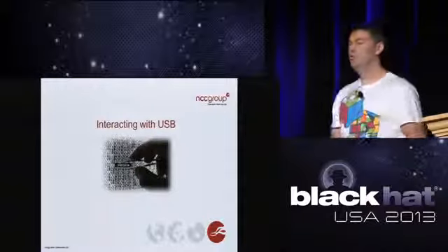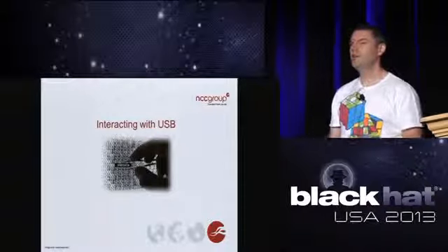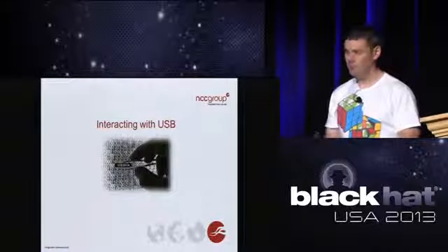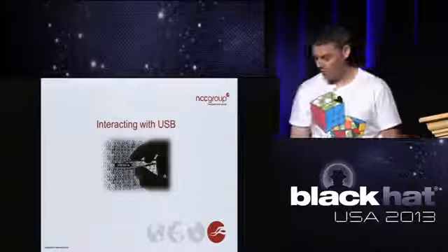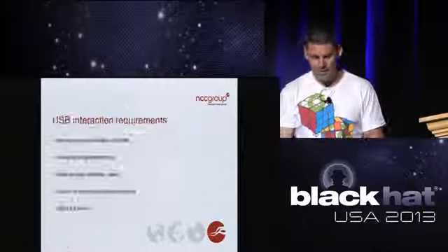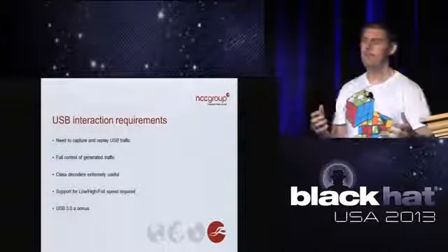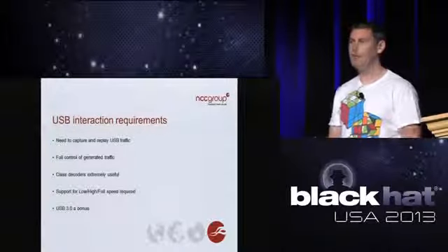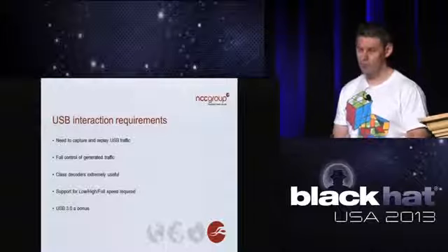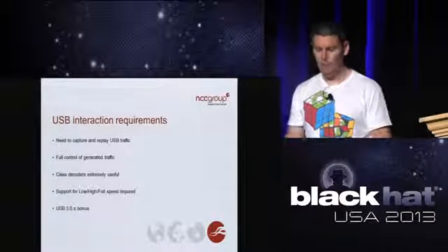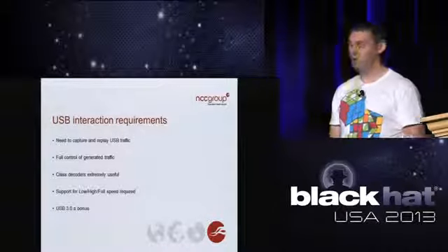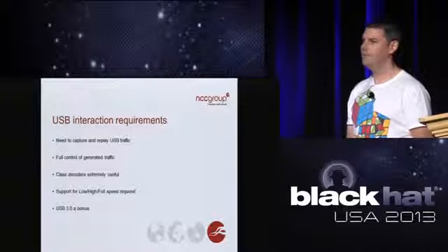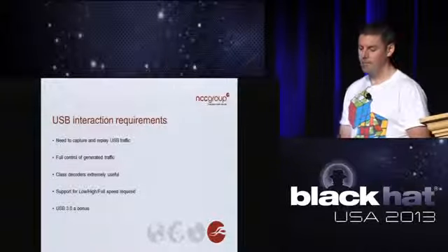If we're going to try and identify information about these systems via USB, we need to be able to interact with it. How are we going to do that? And what kind of areas of functionality do we need to be able to achieve with USB? Well, we clearly need to be able to capture USB traffic and be able to replay it faithfully.